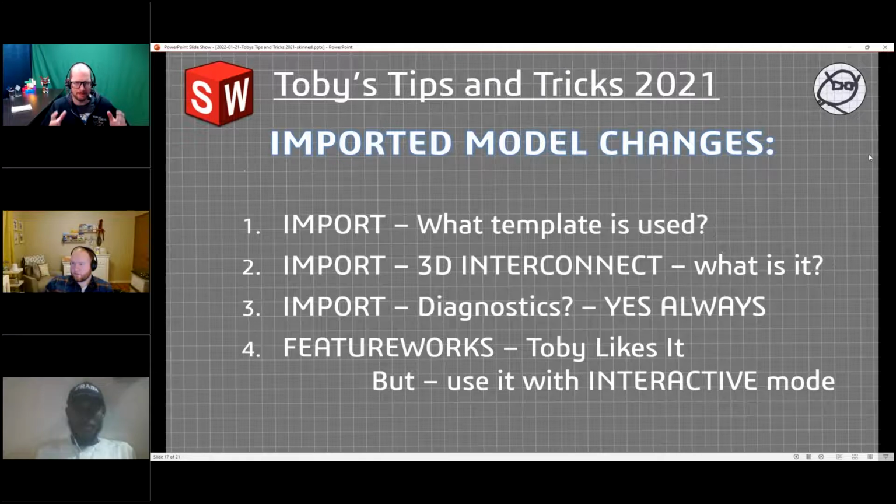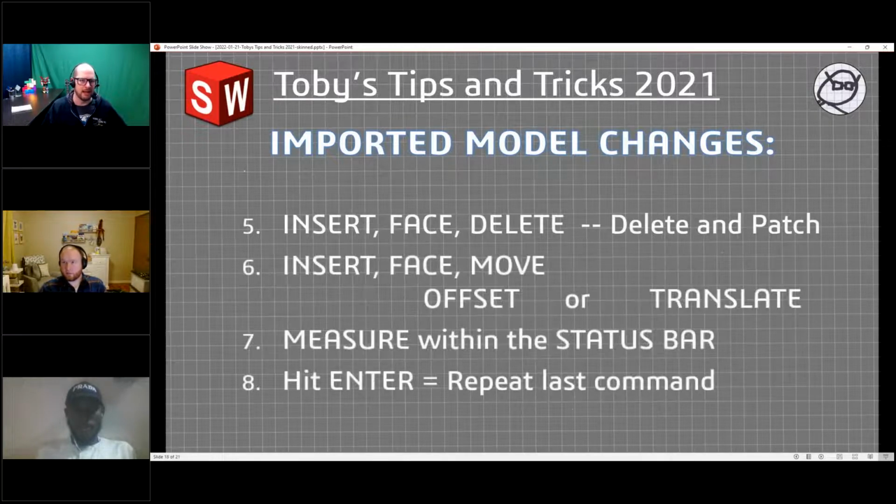We talked a little bit about templates. We talked about the idea of 3D interconnect. We talked about import diagnostics and FeatureWorks, and then we got into the main commands of the presentation: insert face delete, insert face move, measure within the status bar. Oh, hitting enter to repeat the last command, that's another good one.